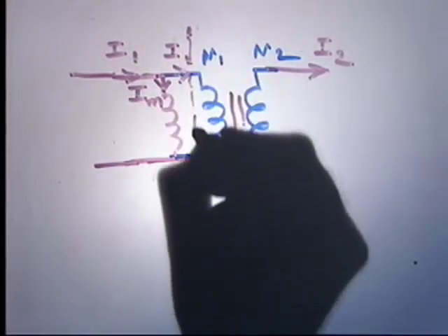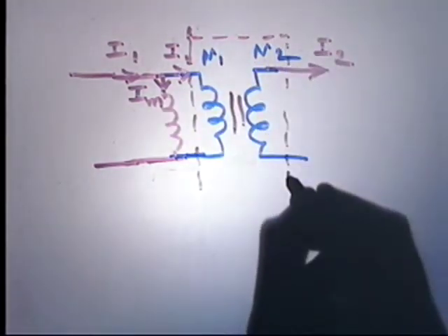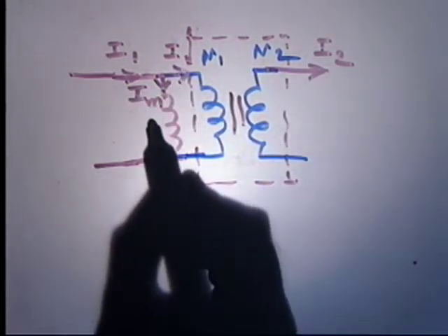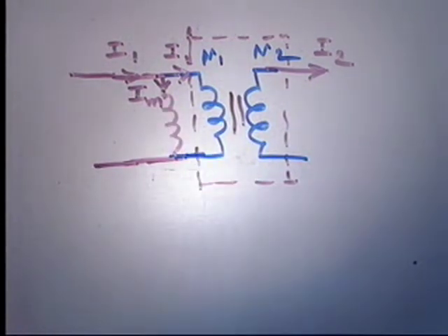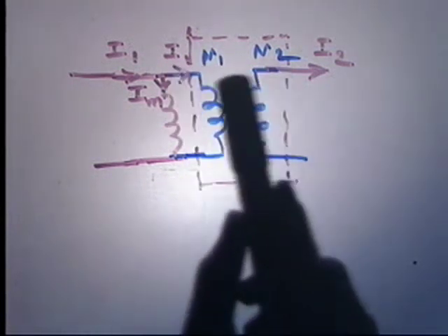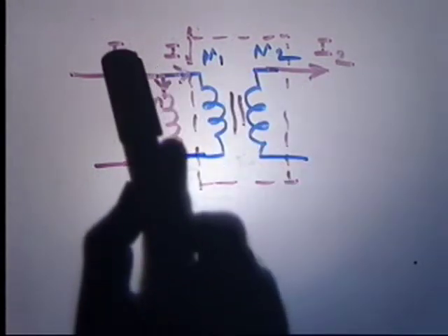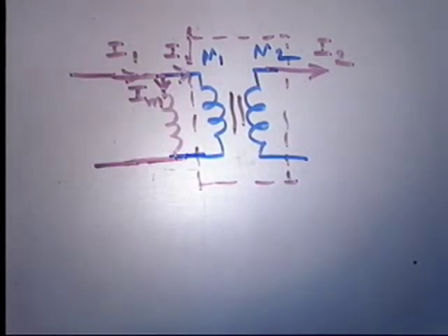This is an ideal transformer, which we had earlier. Now we are having another current. IM means the core is drawing it for flux production. Earlier we said I1 dash N1 plus I2 dash N2 will still be 0, but additional MMF is now coming because of the IM. That added MMF is required to produce the flux. That compensation still takes place ideally, but additional MMF is required because it is not 0 MMF.